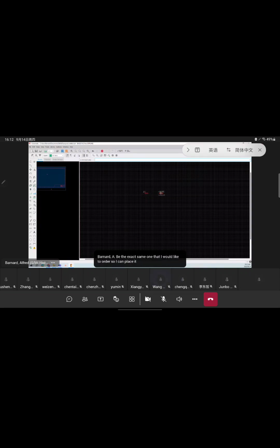So I can place it down simply by clicking. I can right click and then it rotates my resistor. And I usually like to create circuits like this. Press escape once again. Now, as we have seen, our resistors are 1, 2, 3, and 4. We can give them new names, but these names will have to be unique.